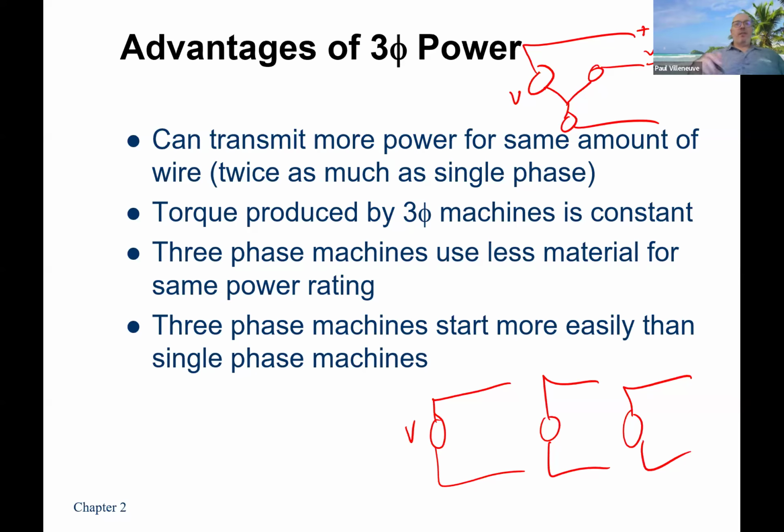So remember, way at the beginning of this class, the transformer that goes to your house looks like this. So let's say it's 7,200 over here and across here to here, it's 240 volt. That's what goes to your stove. The reason why you can plug in is because it's called a center tap and each one of these is 120. So it runs to your house, the single-phase 240, but then you center tap the transformer and then you can get 120 off there as well.